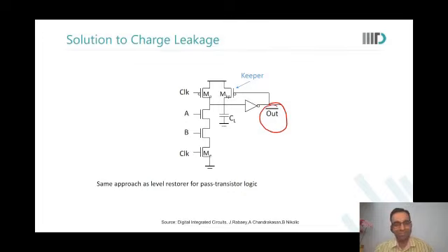Raghav? Sir, you said earlier that dynamic logic is non-ratioed logic. So to maintain that, we had to keep the keeper at 0.135, we cannot increase from that? The keeper, as Madhur also mentioned, is a feedback. As soon as you have feedback, ratioed logic comes in again.